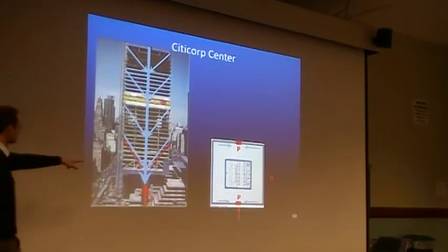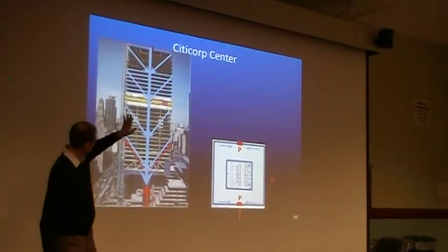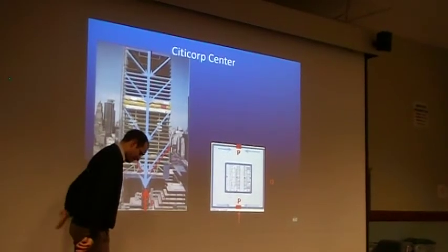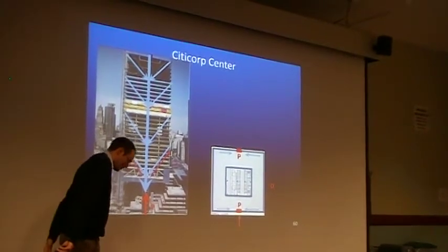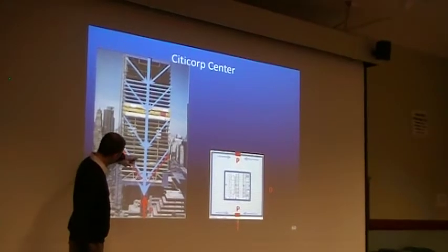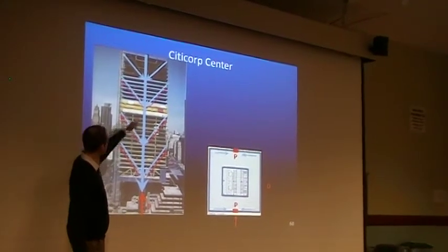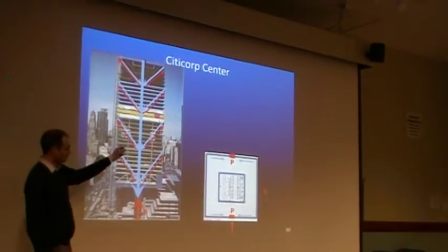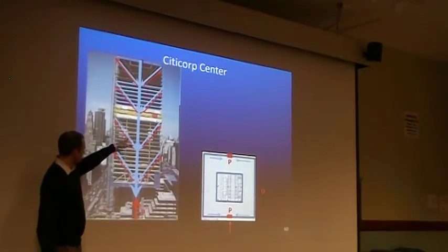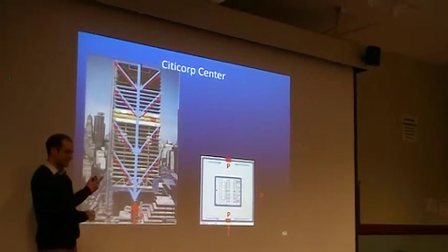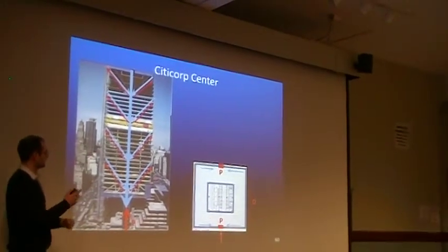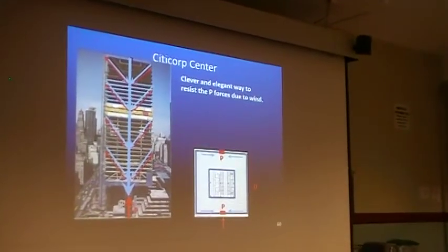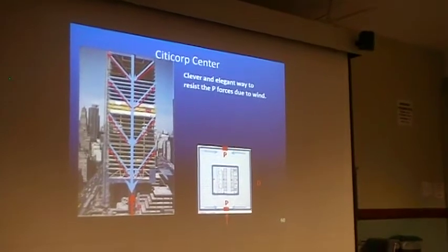These braces do kind of double duty. When this building is getting pushed down, there's this tension load holding your heels down, and there's this tension load that's kind of all along your back, or this side of the building. So these braces all go into tension too. But you work the numbers out, you design the connections, and you work it out slickly so the dead load that's coming down the brace is about the same load that's in tension on it due to wind load. It works out clever. Or slick, these are all adjectives.